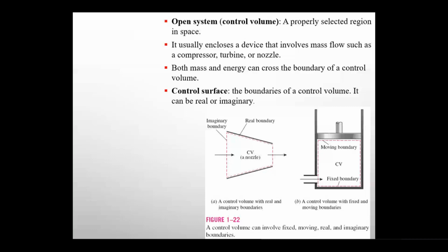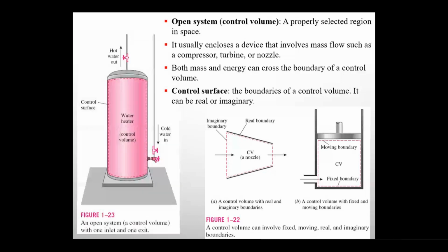Anyways, control volume. So you will have a control volume defined as the geyser and one inlet which is of the cold water and the one outlet which is of the hot water. So there's mass flowing into the system and mass flowing out of the system. Since the only condition for control volume is that mass is allowed to leave the system, you will have it as the control volume.